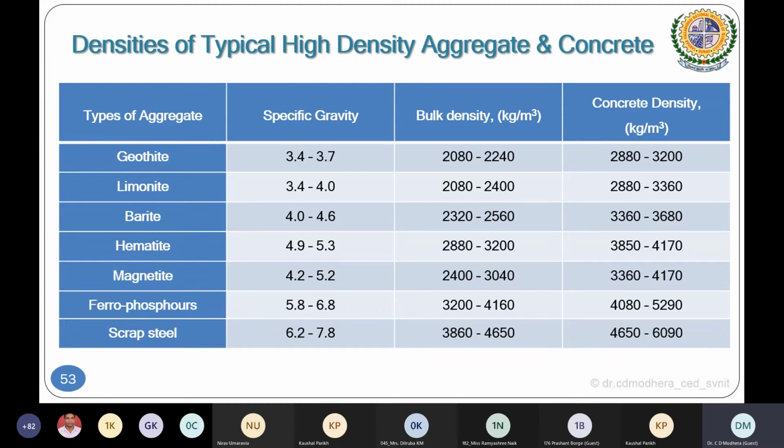So many things are there to get the proper proportion or proper strength. That is why people have worked on some case studies, prepared Excel sheets and calculated the things, the standard deviation, everything they have taken care of. Exposure condition is also mentioned clearly. However, I told that execution is also important. Even batching plants should be calibrated in such a way that they give the correct value of the material. Sometimes they may not. We are very much relying on the digital number. It is showing 25, but exactly it is going 27, suppose. Then time to time calibration of the batching plant is also very much required. Otherwise, the resulting concrete may not work properly or may give different values.